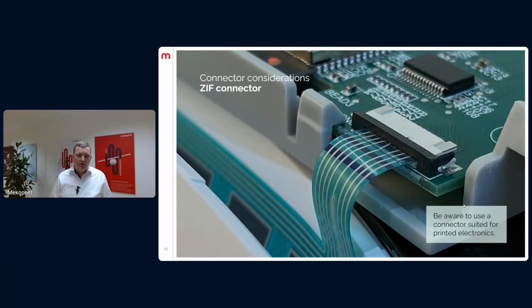We also see that when we choose SIF connectors, the most commonly used pitch is 1 millimeter, but we can also do 0.5. And please be aware that when you choose your SIF connector, choose the correct type, as some are not designed for printed electronics, as they are designed to scrape into the material.